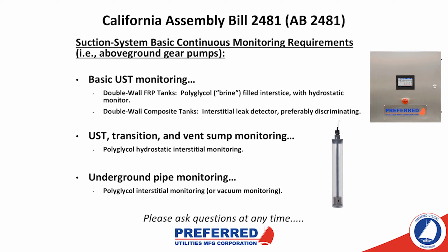As far as UST transition and vent sump monitoring, polyglycol hydrostatic interstitial monitoring is used there. As long as the polyglycol is in stasis at the same level in the sensor, everything's fine. That means there's nothing leaking in, there's nothing leaking out of the interstice.